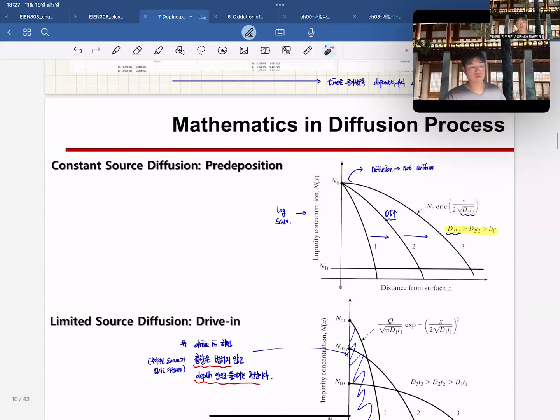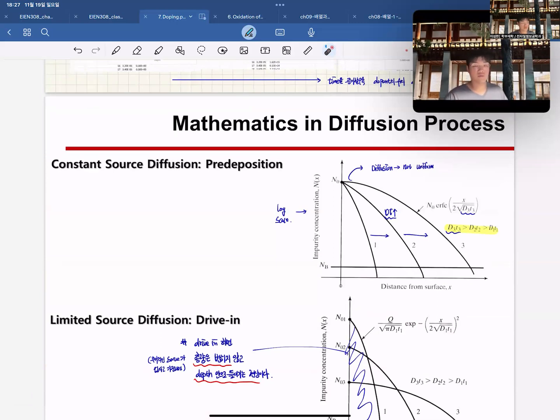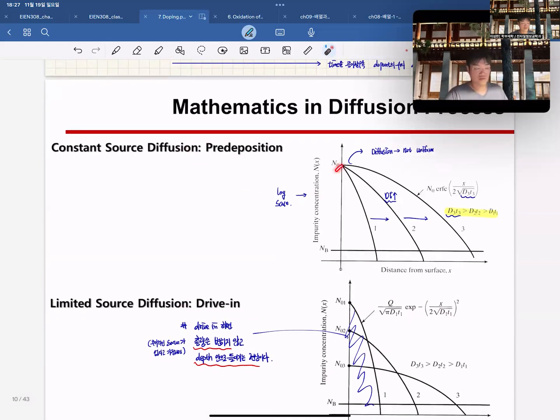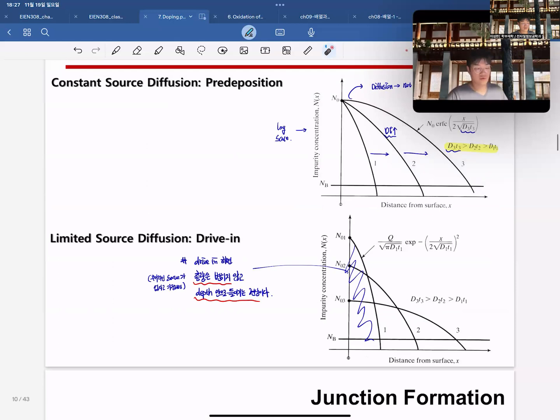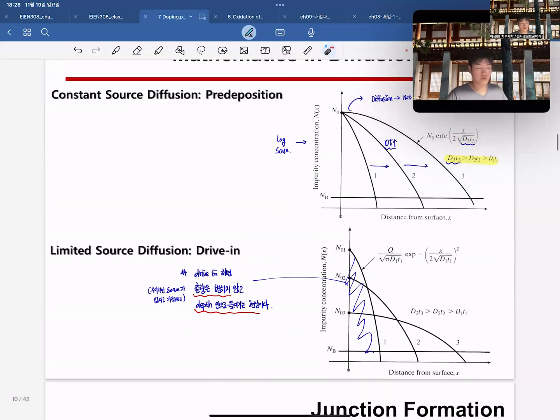And we can see the figure of the pre-deposition and drive-in. Pre-deposition happens at the surface of the semiconductor. We can deposit the dopant atoms here, and we can set a Dt factor. The more we give, the more it diffuses into the substrate. The surface concentration is the same, but we give it thermal energy, and it drives in the dopant atoms.